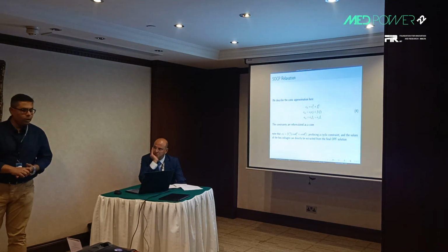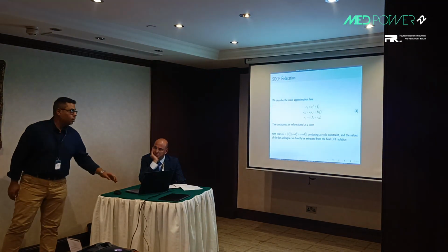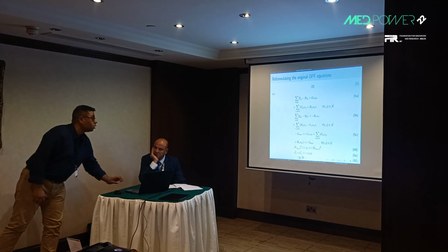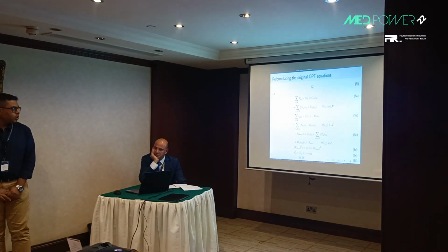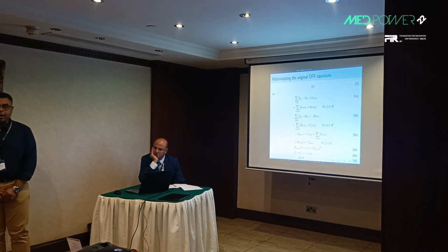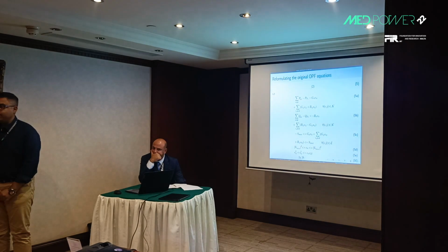That's why we call it a conic relaxation. So we make cones in this. Reformulating the original OPF in cone terms, we have successfully linearized the equations.